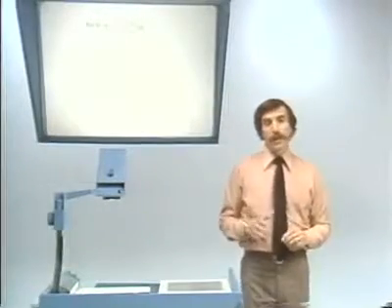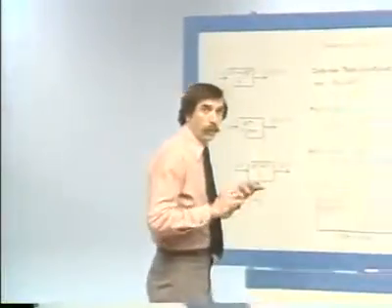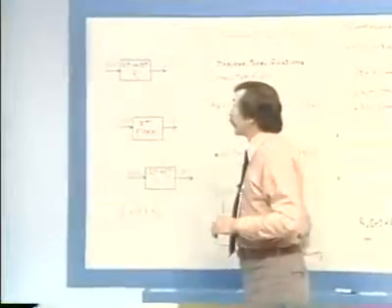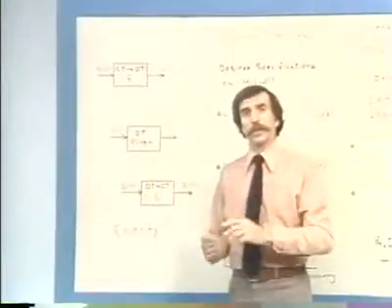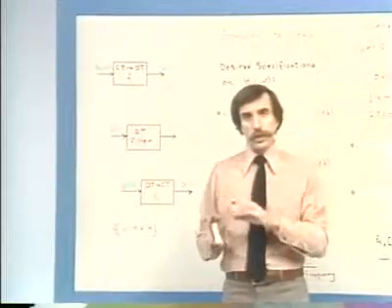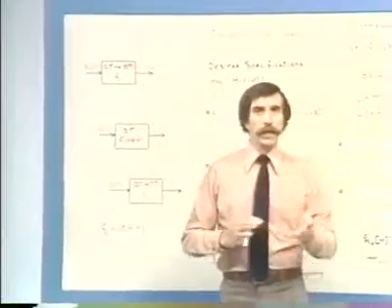All right, so that's what Butterworth filters are. And now what I'd like to do is talk about the design of a digital Butterworth filter using the design technique that we introduced last time, namely impulse invariance. And the context in which I will phrase the design is the context of mapping a continuous time signal to a discrete time signal, carrying out filtering using the discrete time filter that we're designing, and then mapping back.